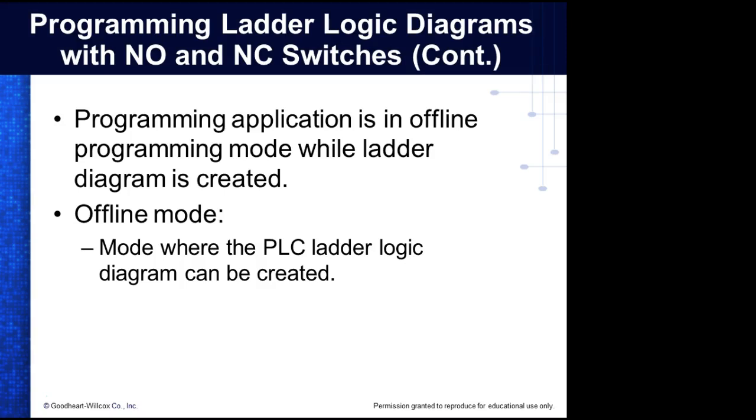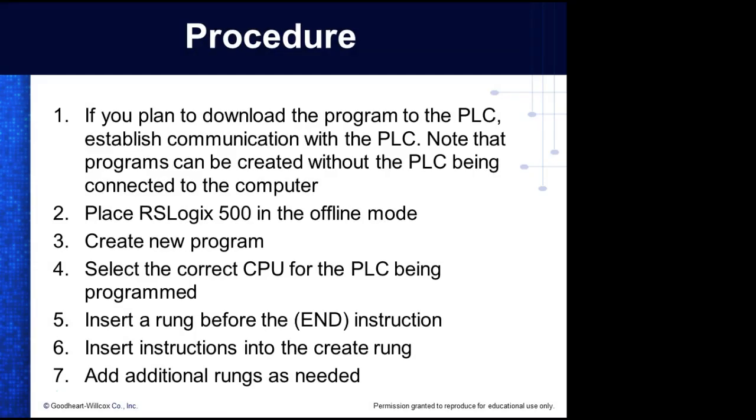Everybody okay with that? While the ladder diagram is created, offline mode. This is where we create the ladder logic. So here's the procedure. This is not in the textbook either. If you plan to download the program to the PLC, establish communication with the PLC. Note that the programs can be created without the PLC being connected to the computer. So if you've got the application on your computer, you can create the programs at home.